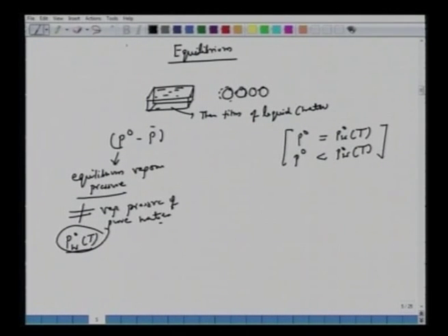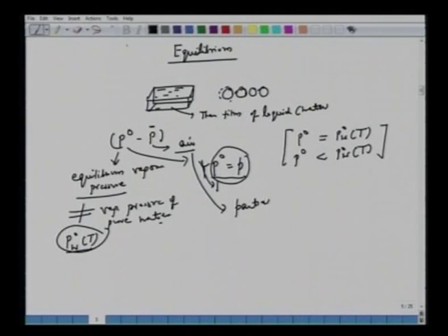So P0 like this, it says equilibrium vapor pressure, how much moisture exerts vapor pressure. So again we can think of this in Raoult's law like Y P0 into partial pressure. So Y is 1, so equilibrium vapor pressure is what we call here partial pressure minus partial pressure in the air. So this is what we are going to control, the partial pressure of moisture in atmosphere.